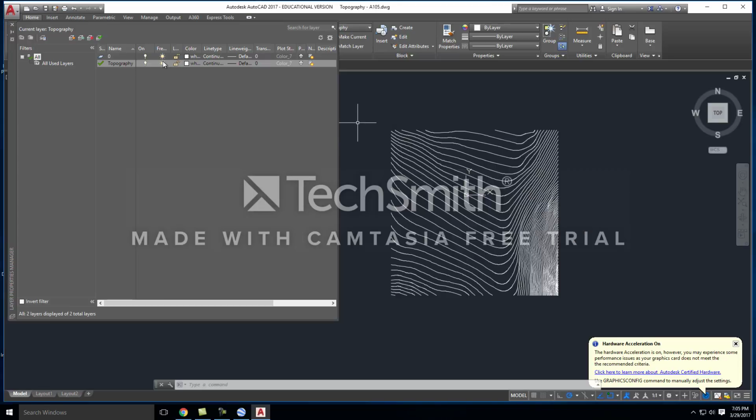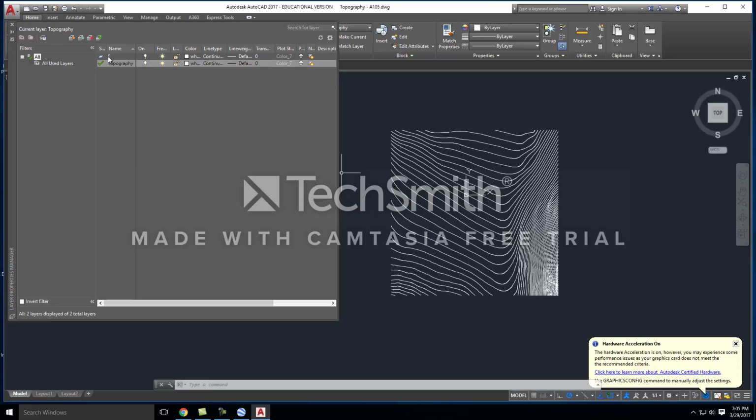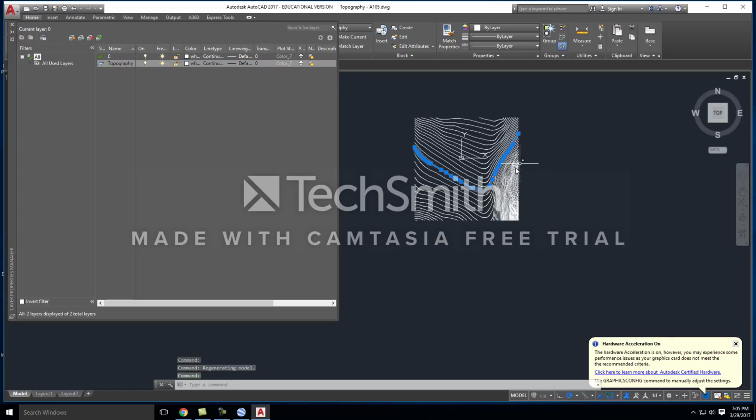The next button is going to be the freeze icon. You'll notice a little sun here. If you click on that, it's telling me the current layer cannot be frozen. So I'm going to make the current layer layer 0. And I'm going to go back over to topography and click on that little sun, and you'll notice that the sun goes from a sun to an icicle. That icicle means the layer is currently frozen, and you cannot make any edits to it whatsoever.